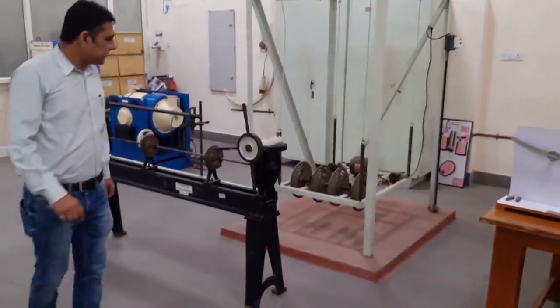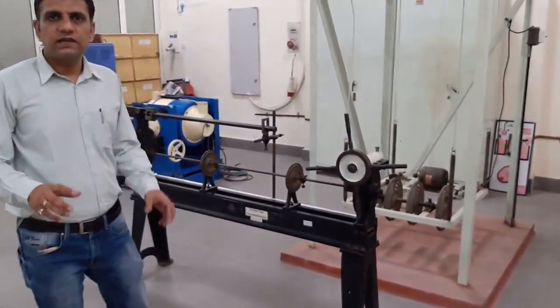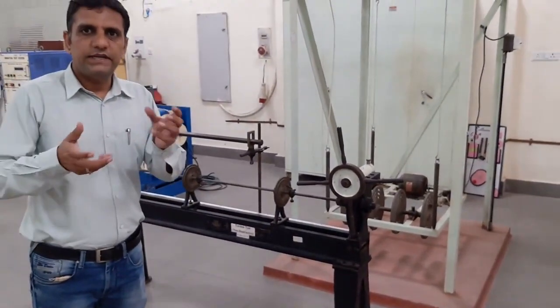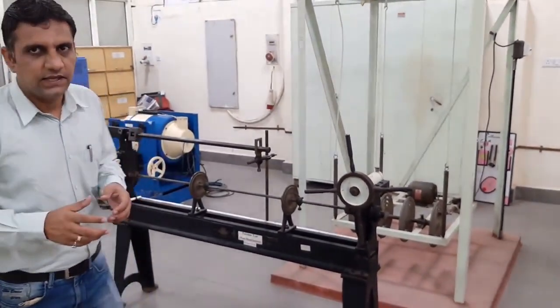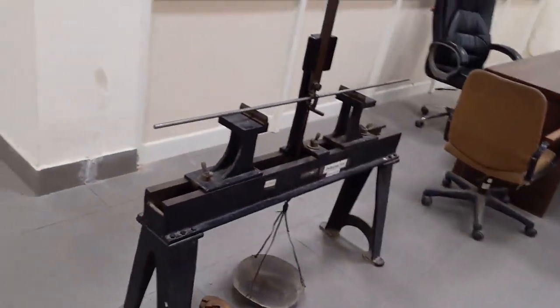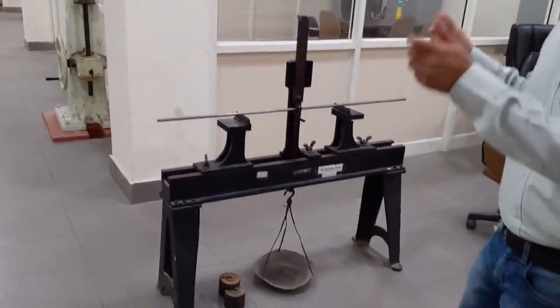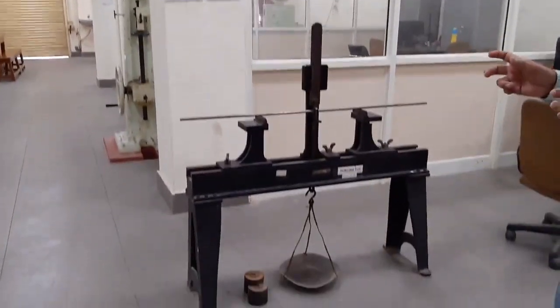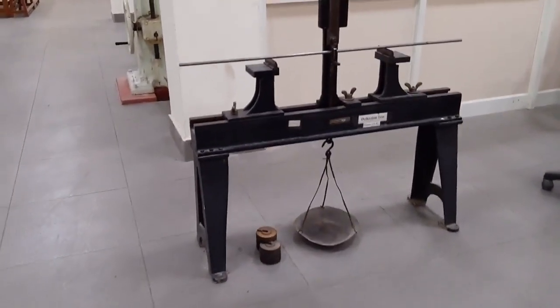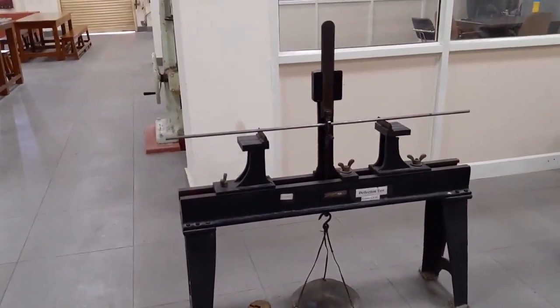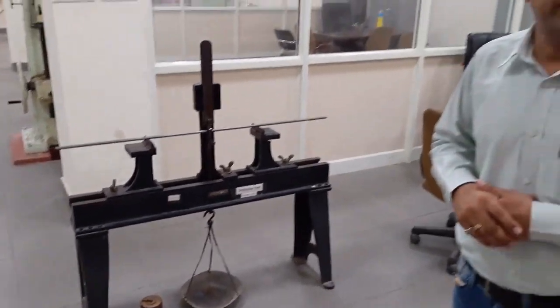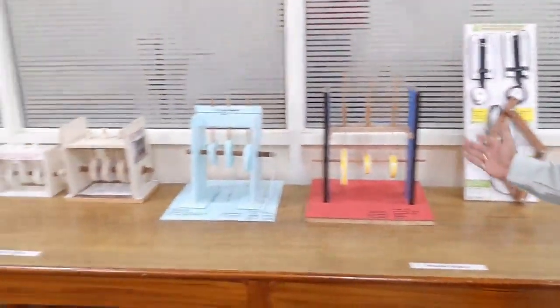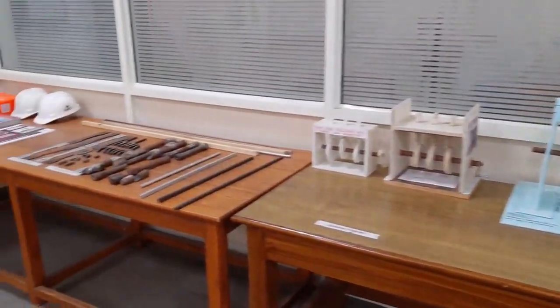In this experiment we have a non-destructive torsion test wherein we do not break the specimen but test the material for its shear strength. In this experiment we evaluate the deflections of beams. We can vary the lengths of the beams as well as the cross section and calculate the maximum deflection of any beam subjected to various types of loading conditions. Here we have certain demonstrations which are made by the students as a part of their project work.